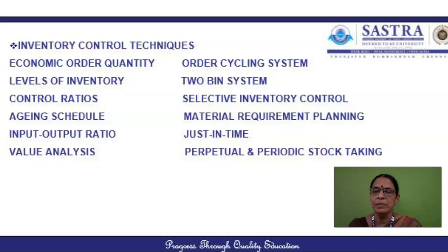Vital items are highly required, essential items can be managed for a day and desirable items can be managed for a week. So the inventory control system can also be made based on this VED analysis. The non-availability of these items may affect the production for an hour, a day or a week.